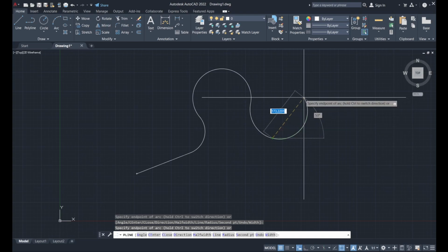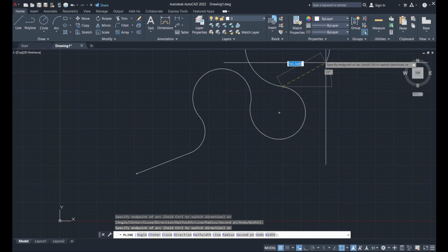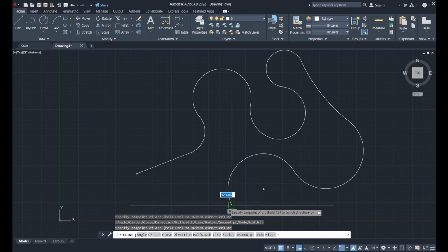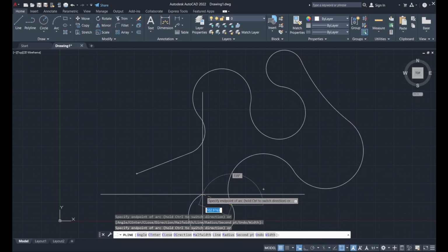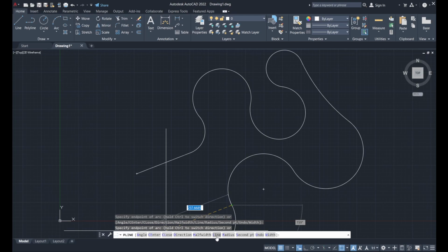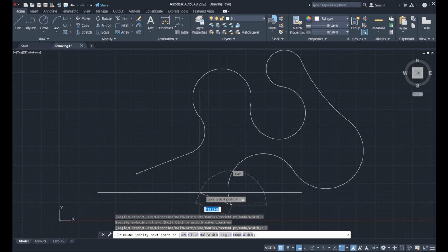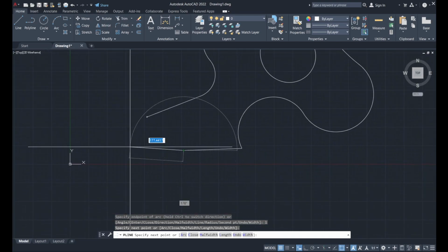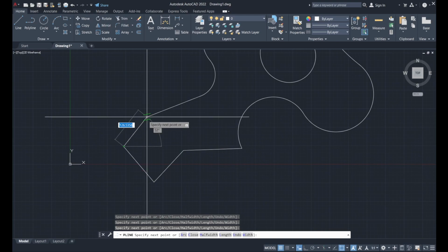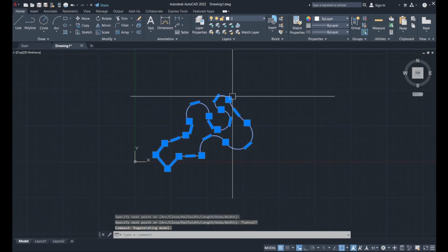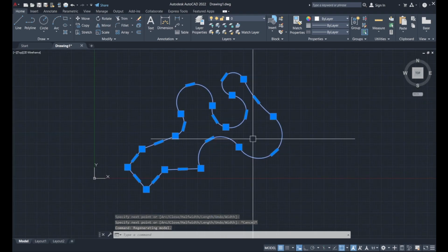And I can keep going like this. Now how I can go back into line drawing mode is, if you see in the command box under line, L is highlighted in the word line. So I'll just press L on my keyboard and enter, and now it has gone back to drawing as lines. And I can just close the polyline by clicking on the origin and escape. Now it has created a polyline with arcs and lines.